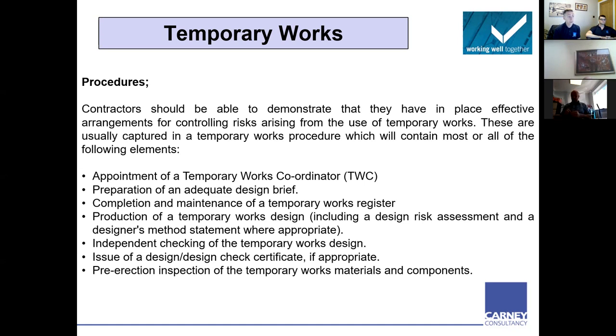Pre-erection inspection of temporary works materials and components. Again, this is something which isn't really pushed, but ultimately it's done by the specialist contractor. So for a scaffold in particular, a design scaffold, they should be doing a pre-erection inspection of all the temporary works materials and components. So, a pre-use check, basically. Next slide, please.